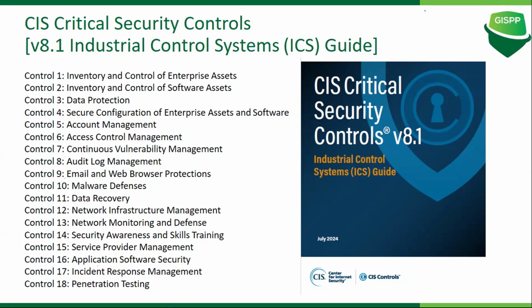VPN. To reach any SCADA system, you need terminal workstations, the engineering workstations. So you can have a VPN up to that engineering workstation. Prior to that workstation, you cannot reach any OT device through a VPN. You can do tunneling, that is something else, but you cannot reach an OT device through a VPN. For that, you need supervisory control servers, computers, which you can access through a VPN.